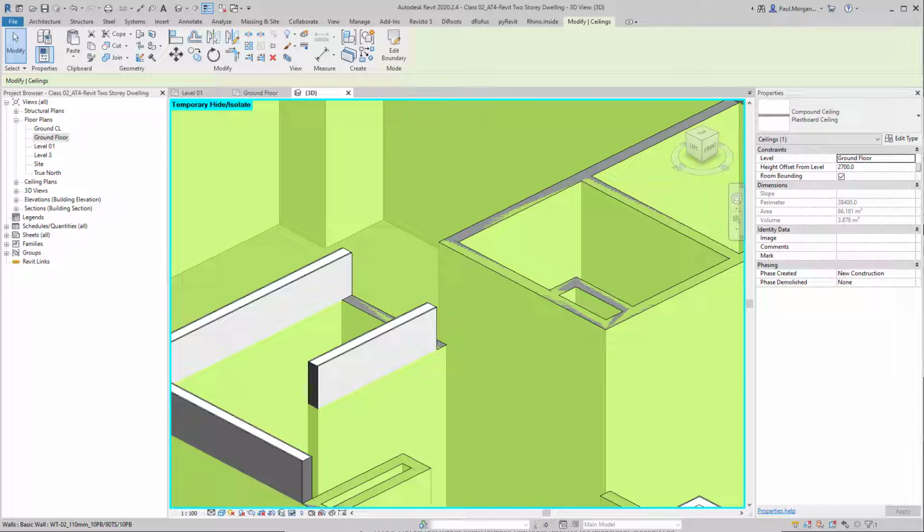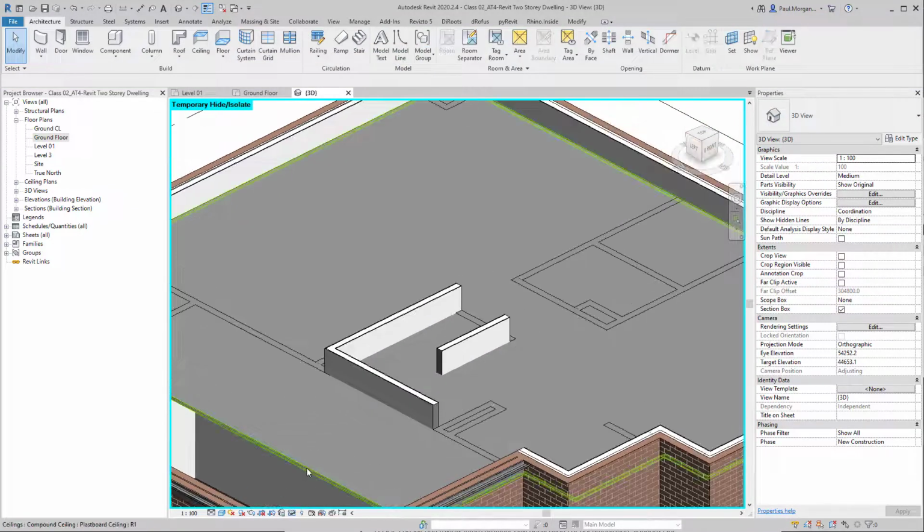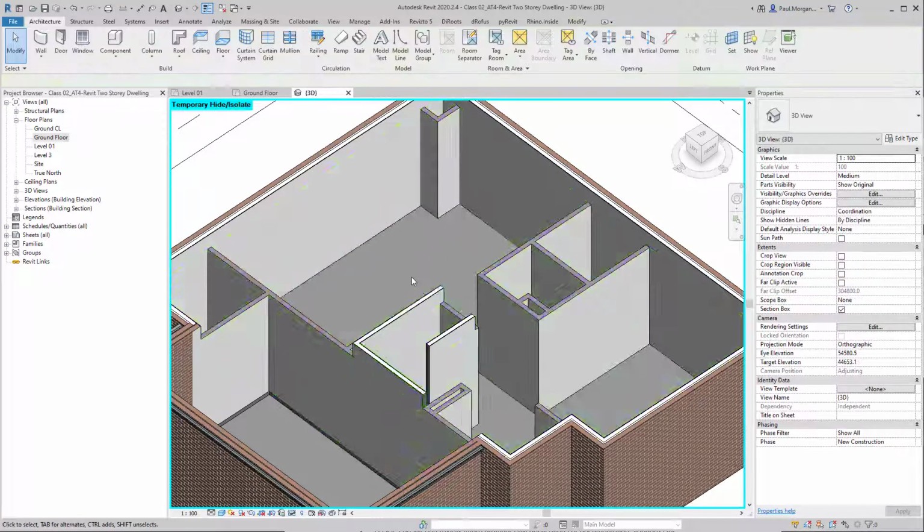And now, again, think about this across, let's say you had 50 levels of a building. That's now 495 square meters that you've miscalculated. That is thousands of dollars in or out of calculation. So this is why it goes back again to Revit being much more rigorous in the method that you model, which needs to reflect the method of construction that's being used. So keep that in mind while modeling your ceilings.